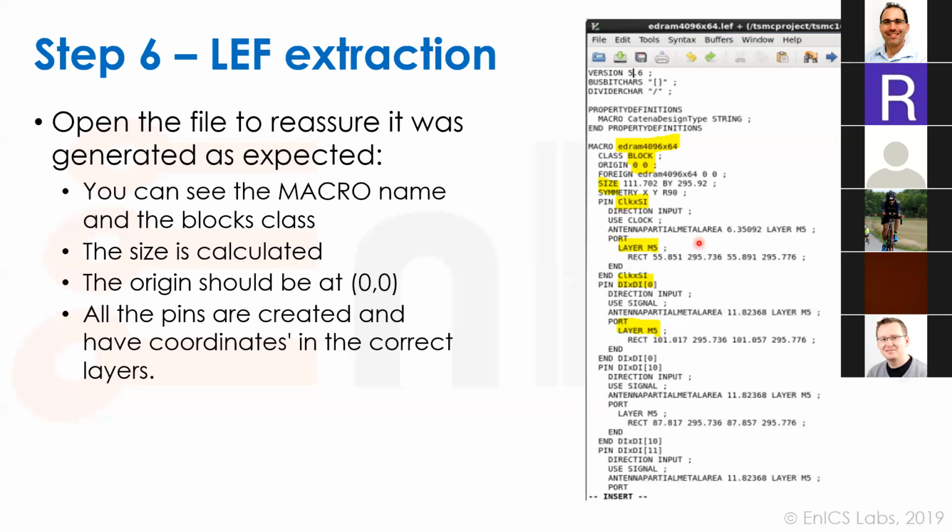You can look at it in Virtuoso. You can import LEF into Virtuoso, but it comes out of Virtuoso, so it's probably the same as the abstract that you see in Virtuoso. But it might be worth doing an import into Virtuoso and looking at it there, to see there is no redundant stuff, that the pins are touching the edges, stuff like this, like zero level verification.